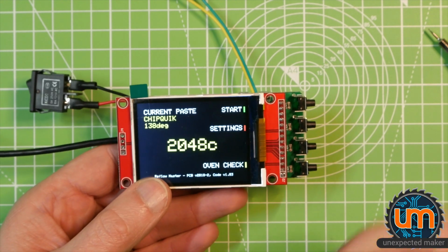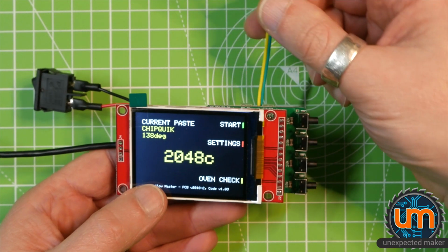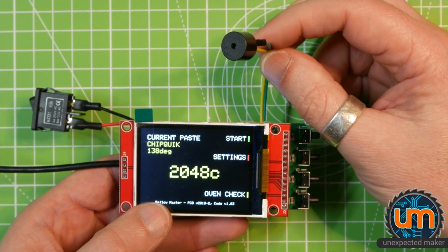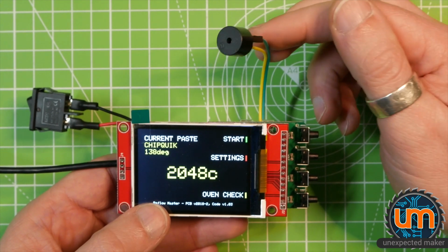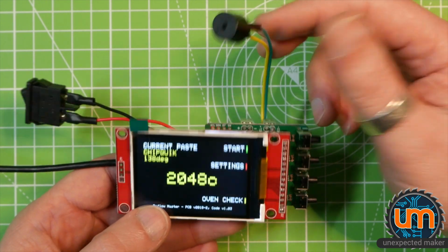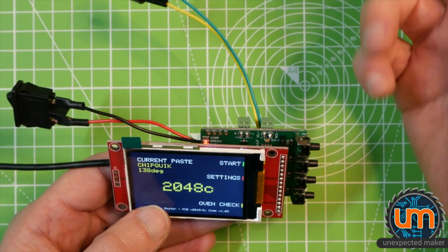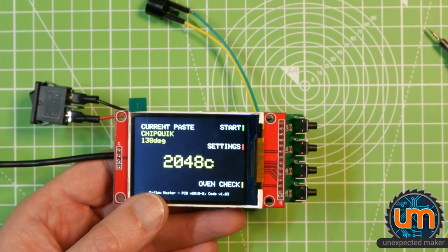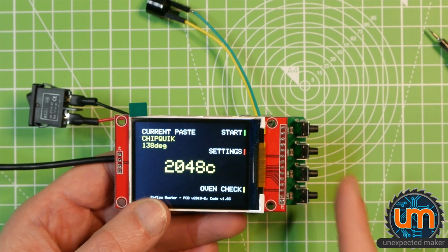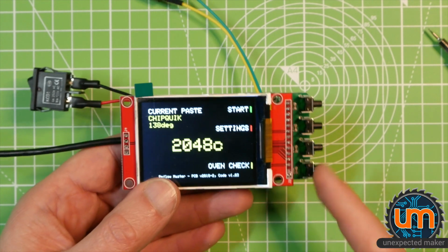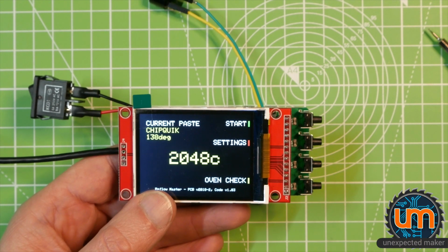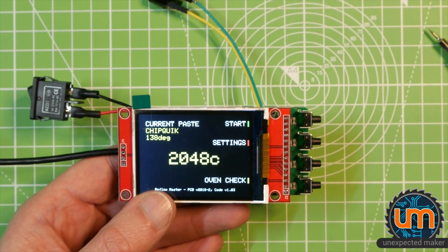Just needed some decoupling across the 5-volt line because obviously we're getting a little bit of backlash or something from the buzzer. Just a bit of noise in general. And just the way I routed the board, I probably should have had a direct 5-volt feed to the screen. The good news is all my current boards are fixable. I can just solder a cap in there, and when I run out of these boards I'll do just a quick revision and place a decoupling cap next to those pins.